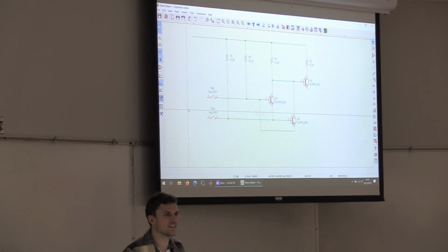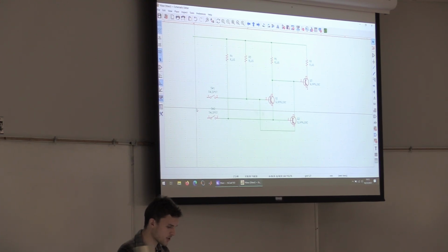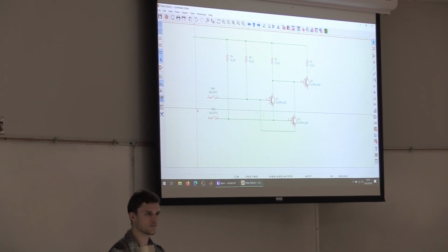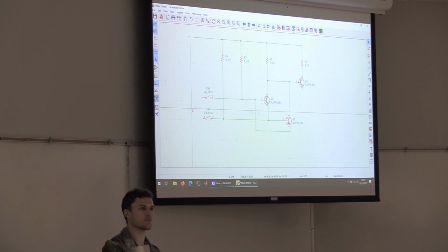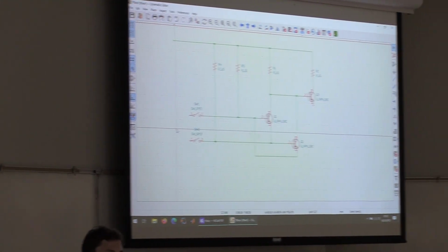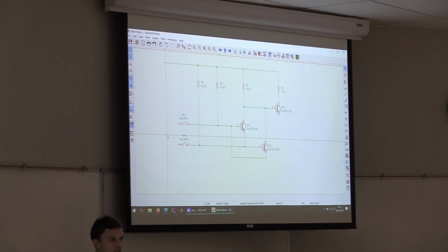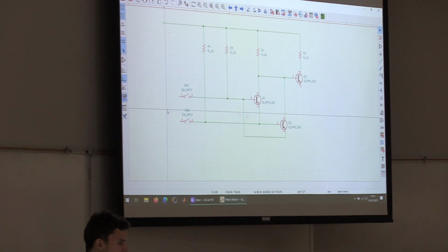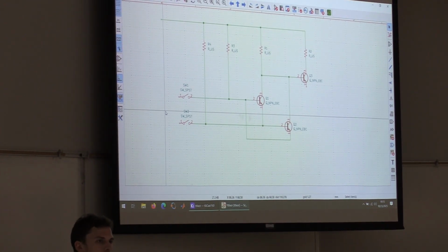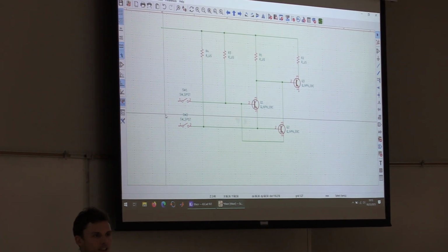What does that mean on a switch? Single pole, single throw, or single pole, double throw. What that means on a switch is the pole is your input, and throws are the number of outputs. So if you have double throw, then you have 2 outputs that you can switch between. And then single pole would be, you have 1 input switching between those 2. A double pole, double throw would basically be 2 single pole, double throws ganged together.